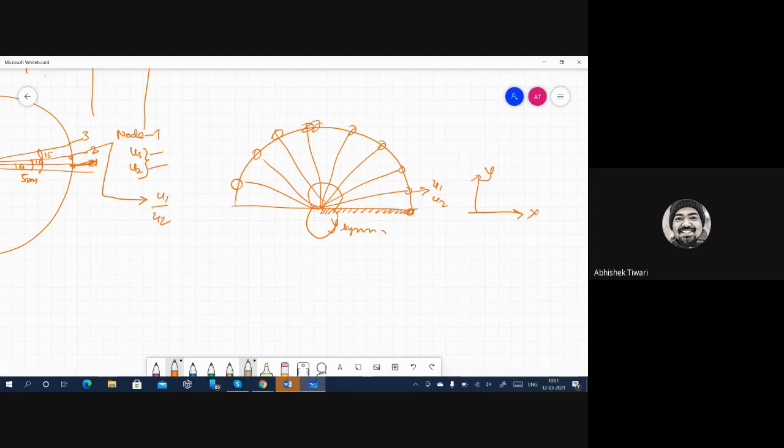Then you go to the boundary condition module. And here, even if you don't make the circle, whatever you have in the module, just apply a boundary condition of U1 and U2 somewhere and record it using the macro manager. That will give you already-written code for how to apply U1 and U2 on a certain node. My suggestion would be that you make this part and mesh it, and then take the mesh in the assembly and apply the boundary condition there.